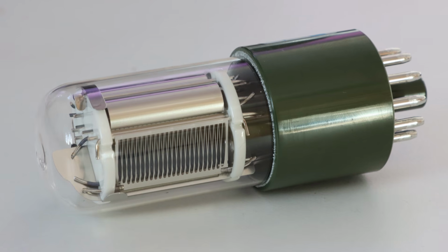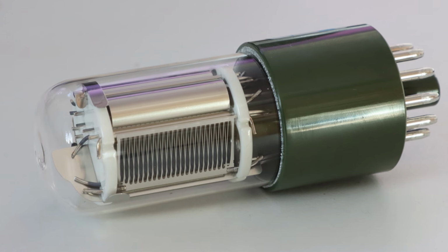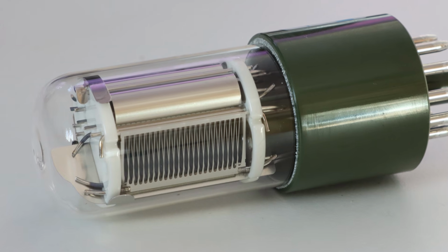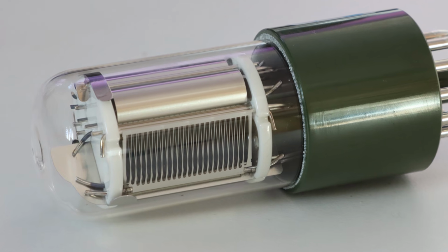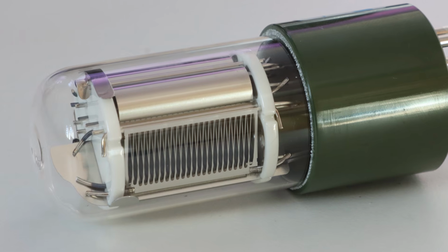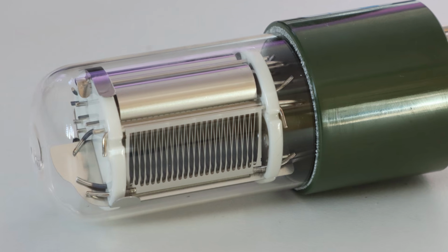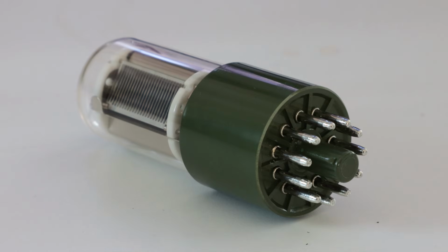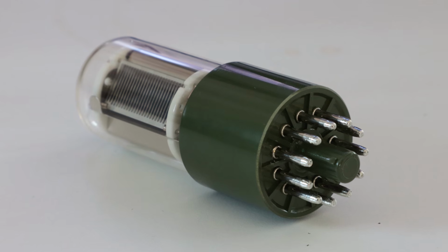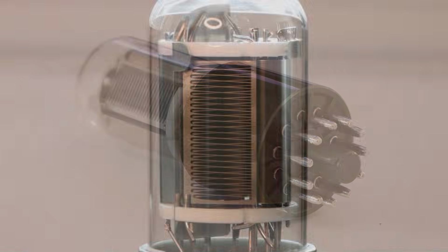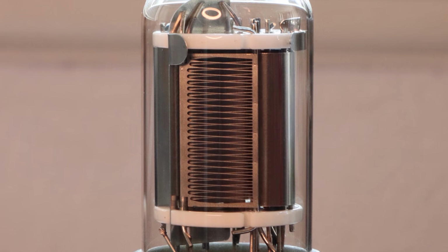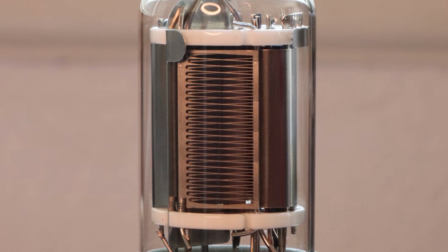In essence, a photomultiplier is a special vacuum tube consisting of a quartz envelope with a high vacuum inside. It contains several electrodes, which are basically curved thin sheets of metal. They are electrically isolated from each other by these two white ceramic insulators, and each of these electrodes is electrically connected to an individual pin on the bottom side of the tube. This here is the sensitive side of the photomultiplier, where light can enter the device through a metal wire mesh.